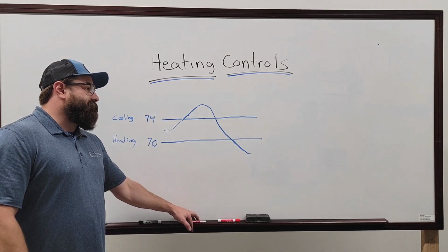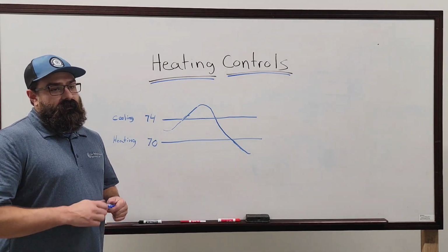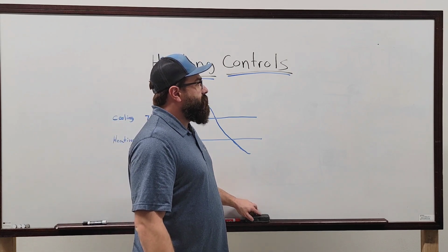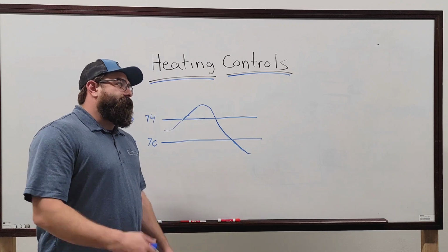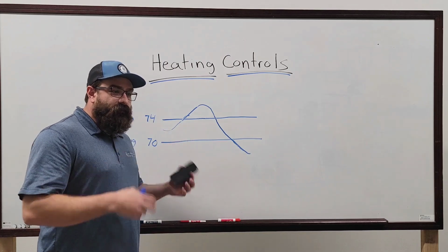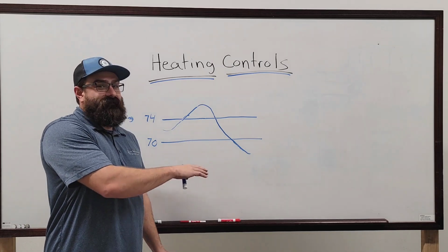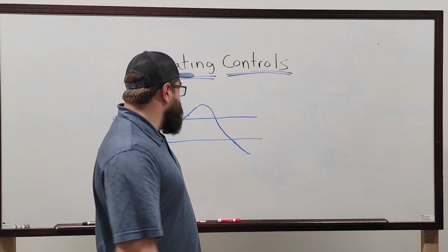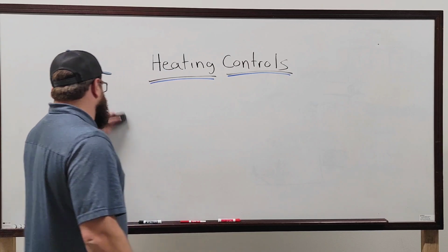So a lot of it is the application of it, not so much the programming of it. But we try not to mess with them if we don't have to. But if I end up with a problem box, like, this lady's always complaining because the fan's running even when it doesn't need to be in heat mode, we can turn that off. I would only do it to that one box unless they request to do it to all of them. And then we know, all right, I messed with that one, I own it.